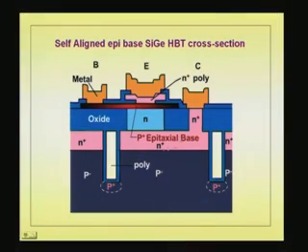So, this is the type of structure that you see. In bipolar technology, in the integrated circuit, you have the P minus layer substrate and N plus collector, contact section from the top, then N type layer collector. You can see the narrow P plus epitaxial base, which is of silicon germanium, and contact is taken laterally there.